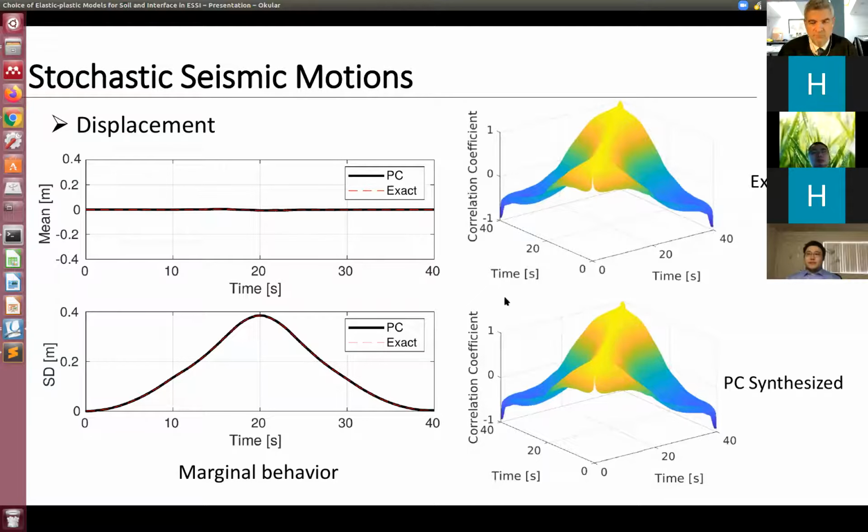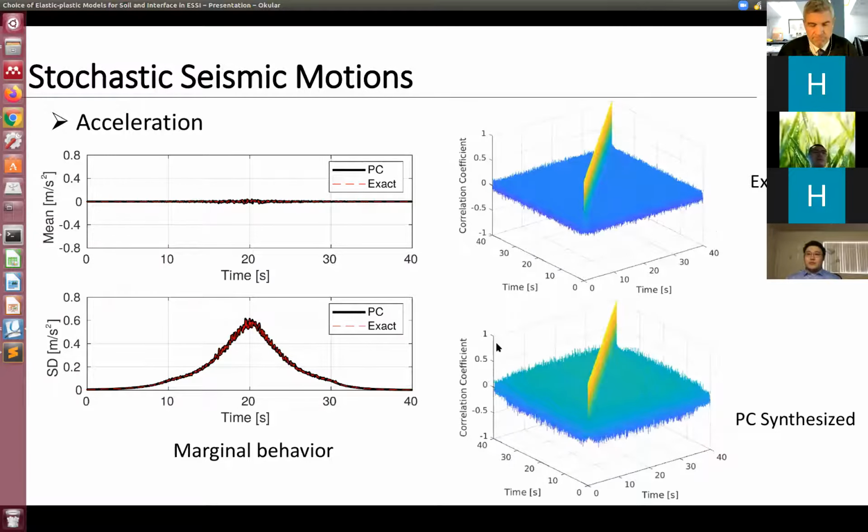So for a Gaussian distribution, generally order 1 of the polynomial chaos is enough to capture the mean and standard deviation. So it's very important to choose a proper number of dimensions of the random process. We also talked about this in our previous lectures on how to characterize the uncertain ground motion. As you can see here, we're choosing 115 dimensions, and it's very easy to capture the marginal behavior, but there is still a tiny bit of difference in terms of the correlation.